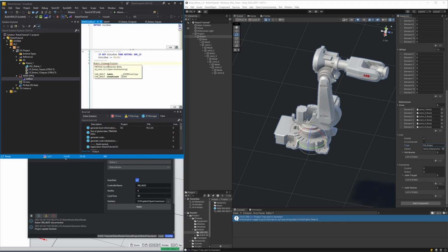And it takes two parameters. The first argument is the axis array of the GVL for the robot, and the number of joints is 6. So this maps the axis outputs of the Robot Studio GVL to the robot behavior model, which enables us to control the robot inside Unity.